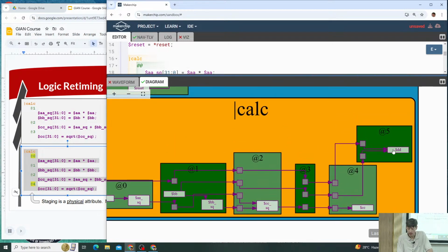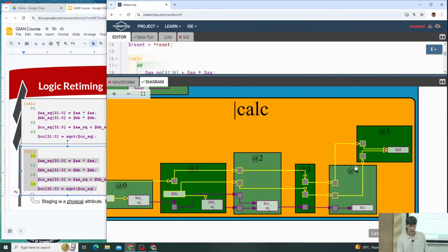Right, so we added this expression, which is an expression of B and A. But A is getting already buffered. That means for each stage what I have. The fact that you have this expression that needs A and B says we need to have flip-flops on A and B to get it to this calculation for D. That means that signal is going to get used in physical space.